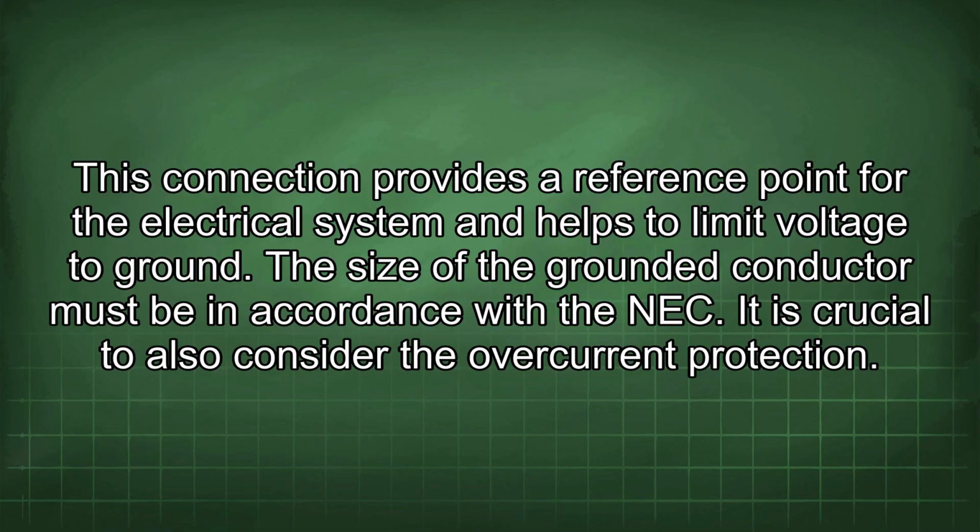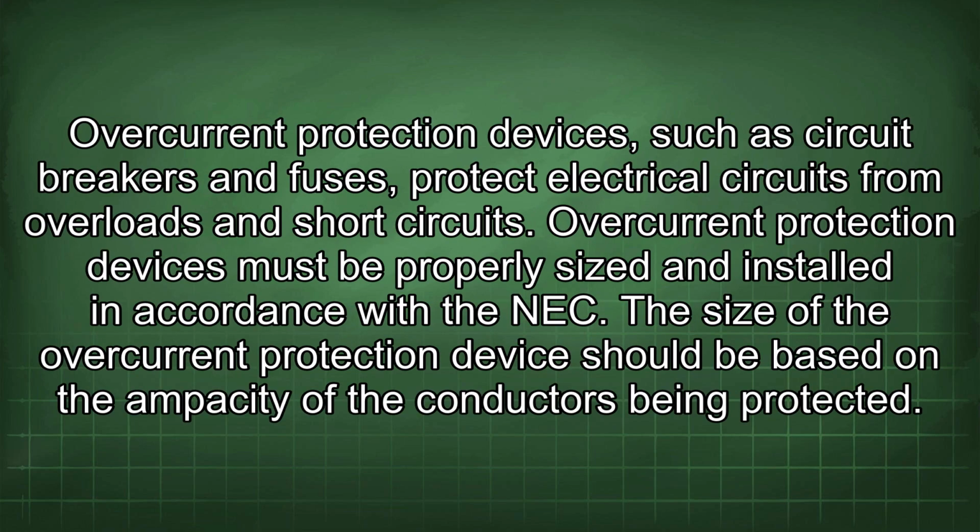It is crucial to also consider the overcurrent protection. Overcurrent protection devices such as circuit breakers and fuses protect electrical circuits from overloads and short circuits. Overcurrent protection devices must be properly sized and installed in accordance with the NEC. The size of the overcurrent protection device should be based on the ampacity of the conductors being protected.